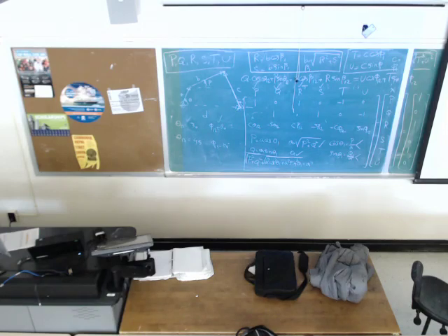But the shortest link is this guy. This is adjacent to the ground. So with this as a crank, this is a crank rocker mechanism. But if you would like to have A as a crank, then you have to change your free choices.